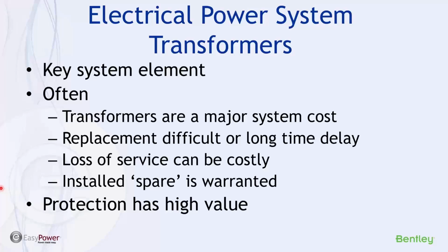Sometimes even an installed spare or speccing out a transformer that has more capacity than required is warranted. But in any case, a protection scheme is justified, and basically you should be looking at the best protection scheme you can afford and make sure you're keeping up with maintenance and monitoring of the transformer itself.